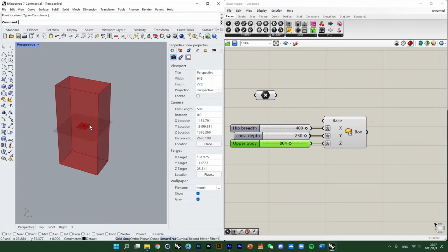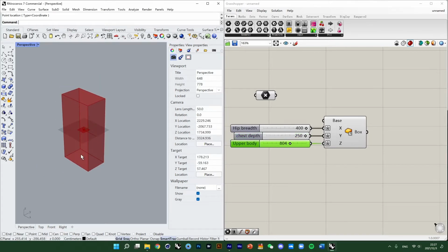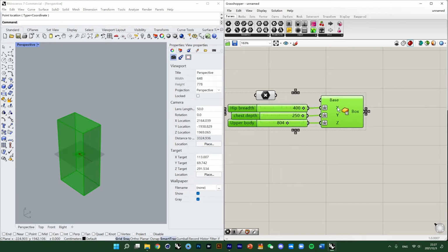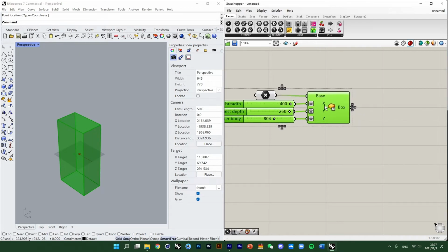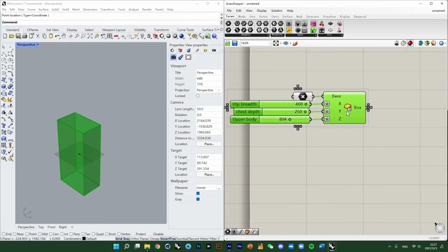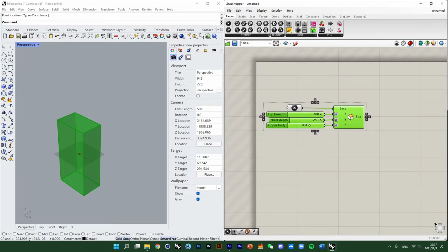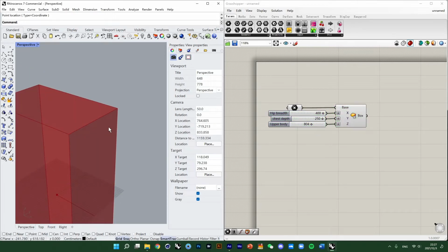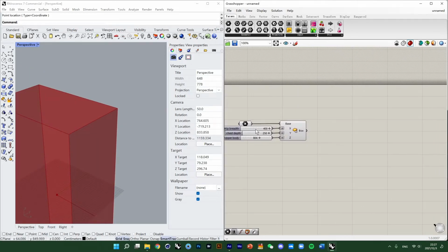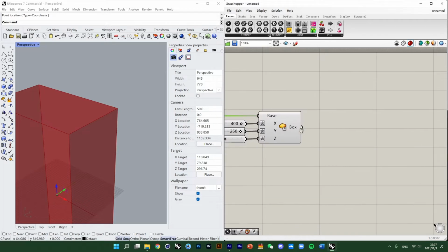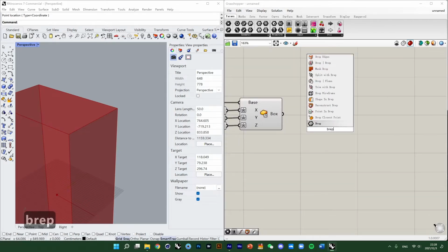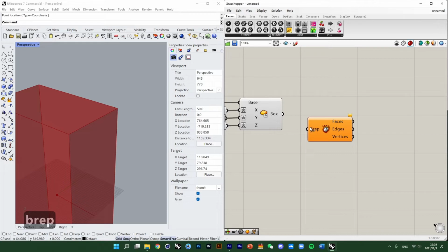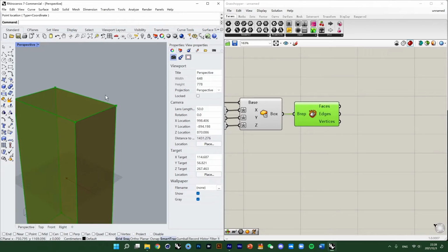And next, we are going to set a plane for our arm. We want it to be located at the center of the shoulder, so that would be the center of this line here. And here we will use several new batteries. First, we need Deconstruct Brep, and this battery is a tool to get the surfaces, edges, and vertices of a geometry, and we can get a panel to see the result.